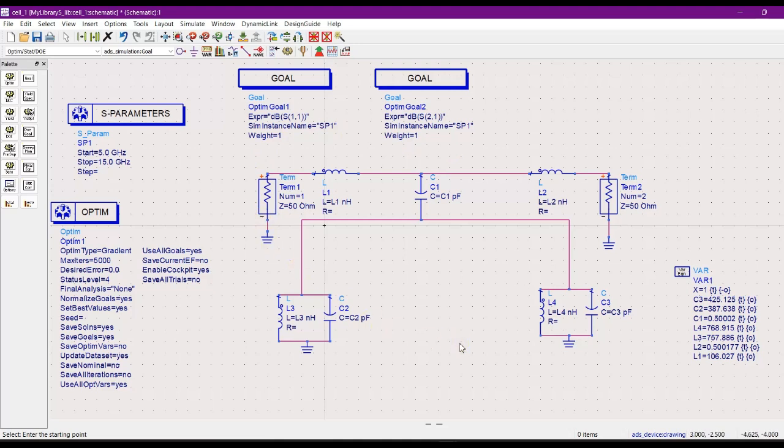Now, in a similar way, you can design an equivalent circuit of any other antenna or electromagnetic device. If you change your geometry, like if you use two inductors and two capacitors in series for the same SRR, then you will find some different values of L and C, so that the circuit is resonant at 12.3 gigahertz.